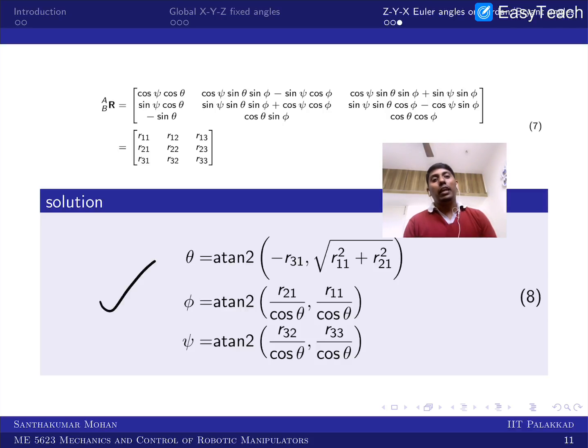The second thing is, for any body in 3-dimensional space, you need 3 positional variables and 3 orientation variables. In the sense that if you have n bodies, you have 6 times n variables to describe the system, right? This is the truth. Can we simplify or modify this? For that, two popular approaches have come. One is the transformation matrix approach. The specific approach we are going to focus on was given by two popular researchers, Denavit and Hartenberg. They gave the DH representation, that is one thing.